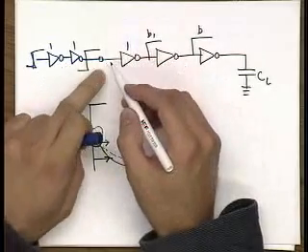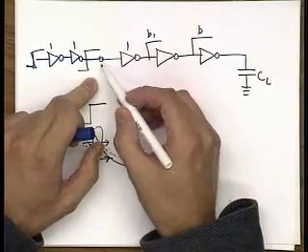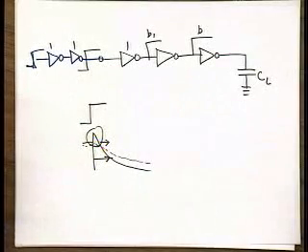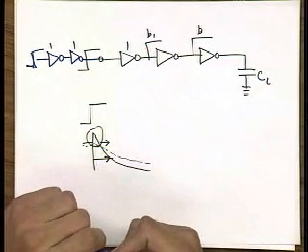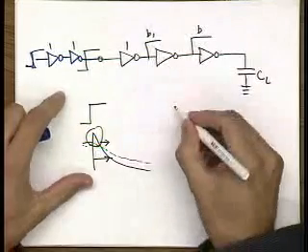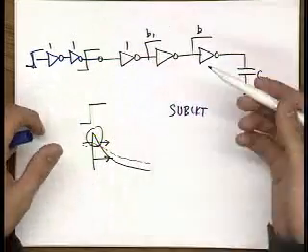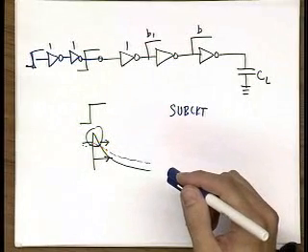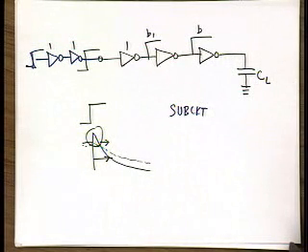And that's what you're going to be using for SPICE verification in your homework and also later on for the project, just to make sure that you have a realistic driver for your input gate. And also a hint, you will see that more in the document that we will post. It's useful to use the subcircuit command in HSpice to replicate all of these inverters. So you create one inverter with parameterizable WP and WN, and you just apply a scaling factor to get these inverters with a larger size. Okay?